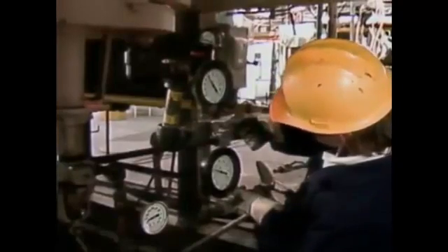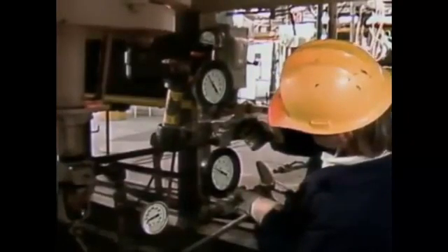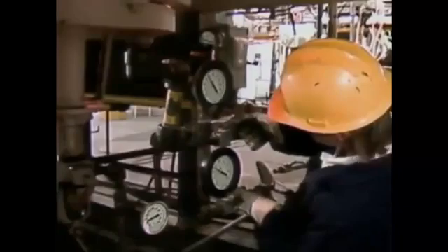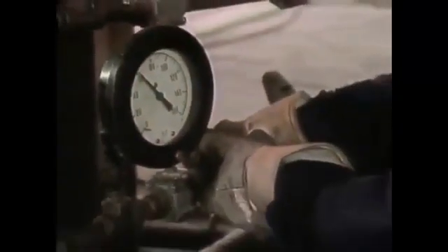Oil burners are operated a little differently. With an oil burner, besides adjusting airflow, another way to manipulate the flame pattern is to adjust the atomizing steam flow. For example, by adjusting the steam flow to the atomizer, you can adjust the length of the flame. The fuel oil pressure to the burner can also be adjusted.